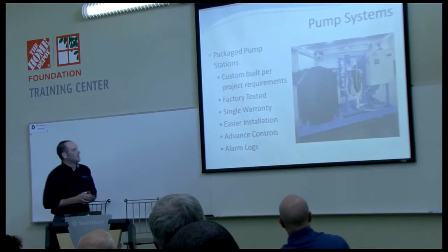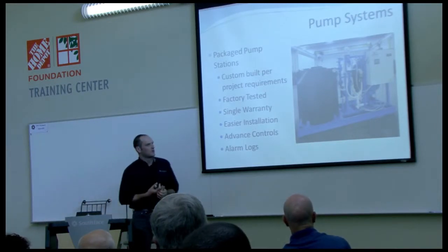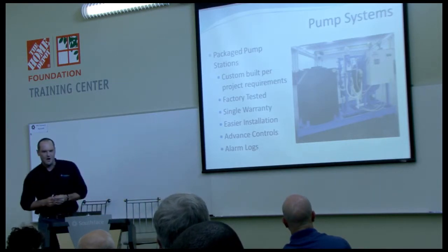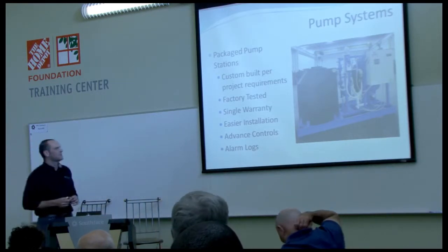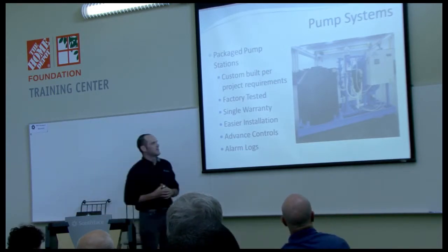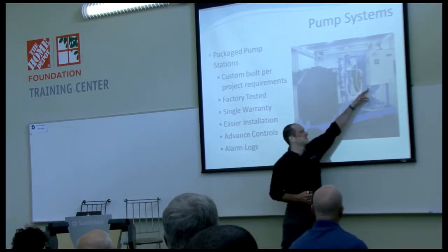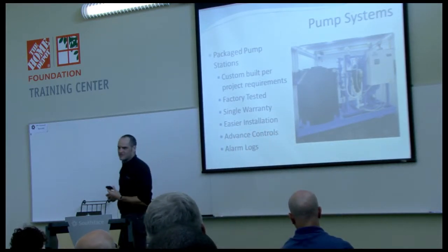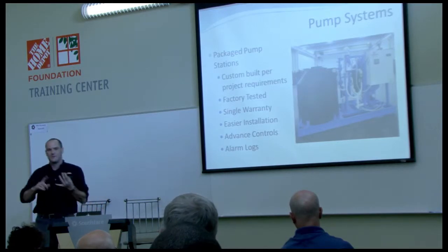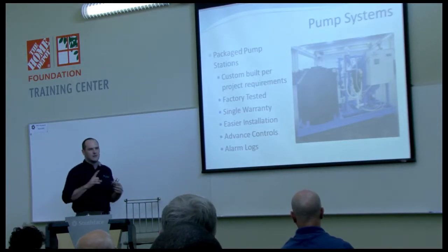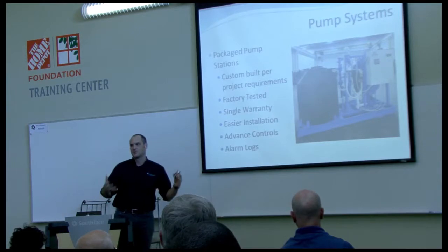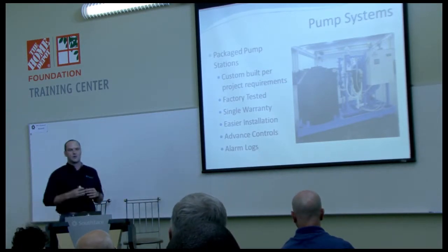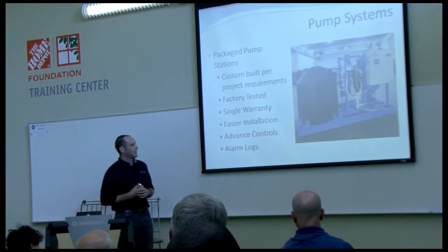Then you would move over to a package pump station. These are usually larger commercial applications that have higher volume and pressure needs or more control needs. This is a package pump station. That's the control panel there. You can tie that into a building monitoring system and get real-time feedback about how much water is in your tank, whether the pumps are running, what type of alarms you have, which especially becomes important for LEED-type operations where you have to quantify how much water you're saving over your baseline, that sort of thing.